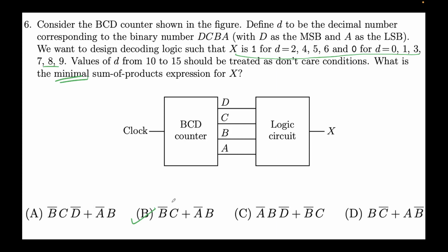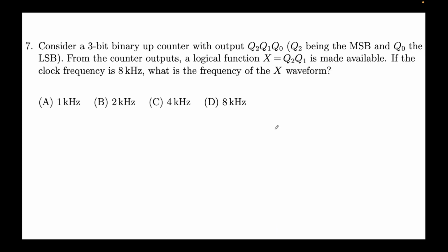Okay, this is a good example of how sequential circuits involve combinational logic as well as sequential logic. Here you have some flip-flops, here you have some gates, in this case a NOT gate and an AND gate, and again here. So this is a combination. This is how circuits actually look in real life, and this is a good example of that. Okay, let's quickly move forward. We are running a bit short of time.